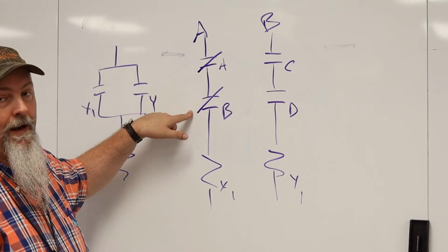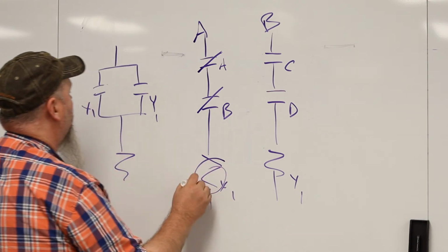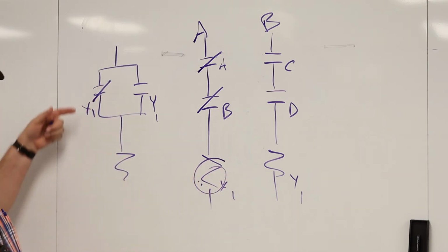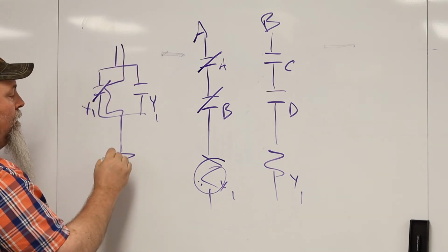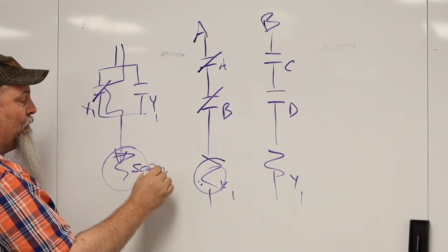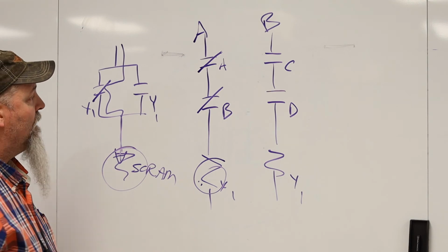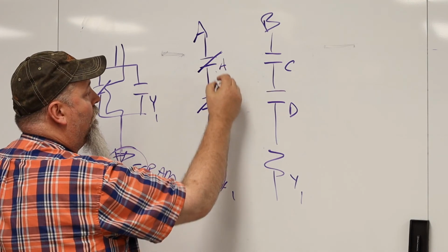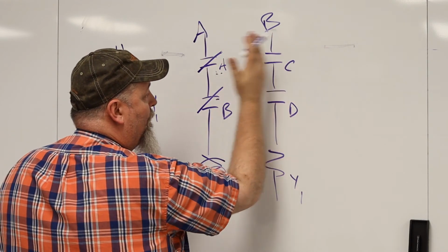So I get a signal on alpha and bravo that energizes this relay, which closes this contact, the X-ray 1 contact. I now have power to this relay for the scram or whatever, the actuation, the isolation for that circuit. And it's 2 of 2 taken once. I don't need both.